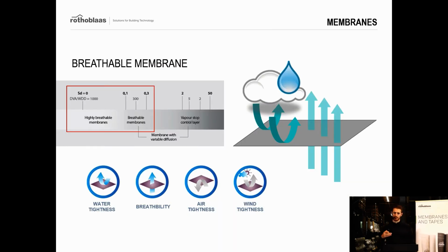And on the outside of the wall, of course, you have to prevent water to get in. You have to make sure that also the wind is not getting in, because if the wind gets in, the temperature of the insulation layer, for instance, is dropping down, and we explained before that if you have low temperature and the same amount of humidity, the condensation risk increases because it's easier to reach the dew point. So on the outside of your wall buildup, you can place the breathable membrane.